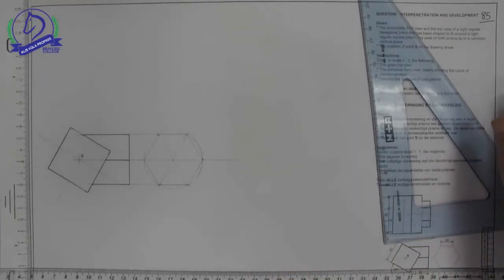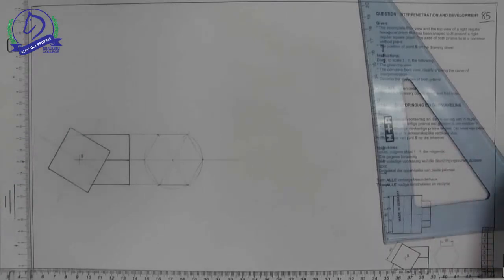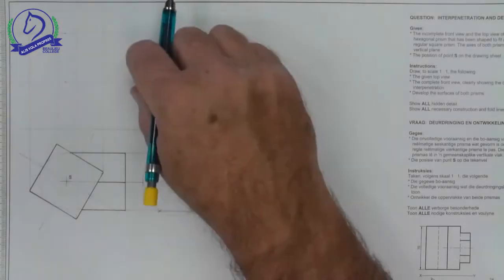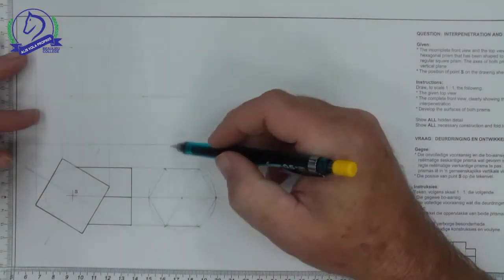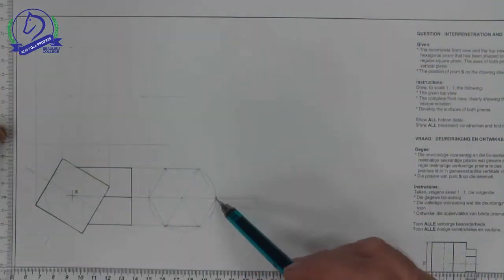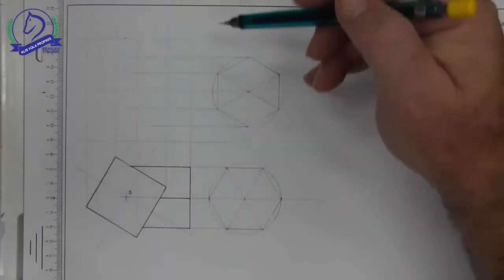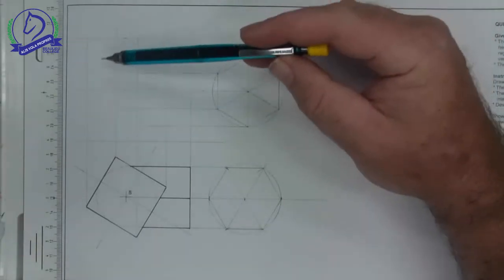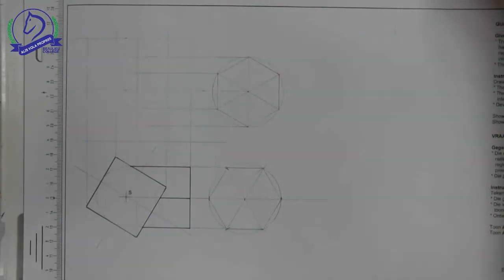There is the outline done, and now I'm going to project my lines up to get my front view. I've projected my lines up to the front view, and I'm now going to get my height. I'm now going to also do a construction of my hexagon on the side. Remember, between the views we need to rotate 90 degrees. So what will happen is that the point will be at the top of my shape. There is the outline of what I need for my branch pipe and my main pipe. I'm just going to go over a certain amount of this in an outline, and then we're going to start working on finding the curve of interpenetration.